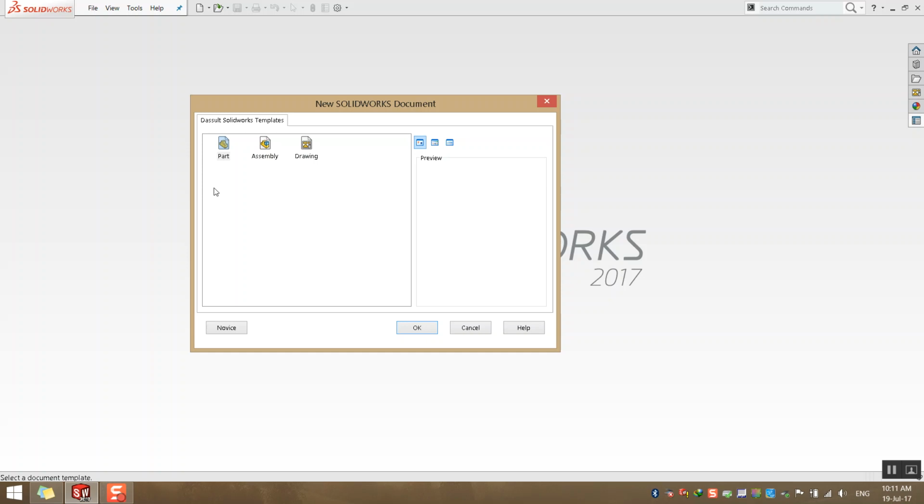In assembly, I will test the motion if the assembly has a special motion, install screws, nuts, washers, all accessories and fittings, and check dimensions. After that, you will export drawings for manufacture. Drawings include tables with an ID, job number, part number, material, and quantity. All information about the drawing will be exported from this environment. This is the full process of your production.